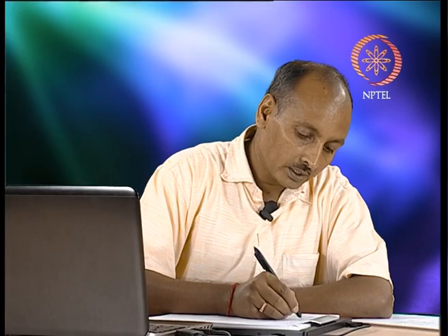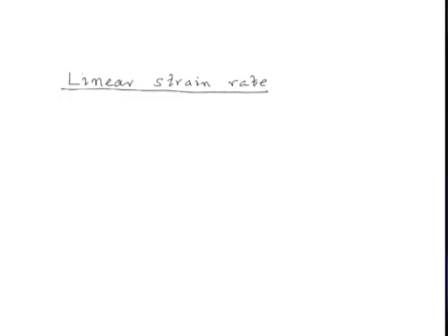Next, let us have a look at the strain rates which we would frequently use in the description of the fluid motion, and first let us concentrate on how we would define linear strain rate. It would be worthwhile to note that in fluid mechanics we do not talk about a strain per se, because that is meaningless for a fluid medium. So, we always talk in terms of the rate of linear strain or rate of shear strain. Now, how would we define this linear strain rate?